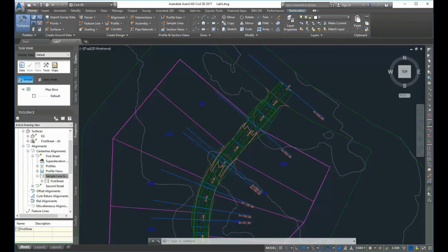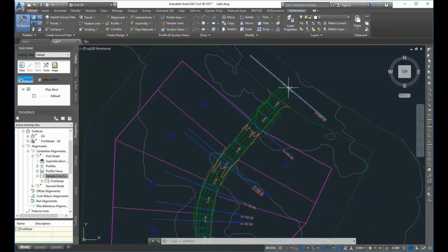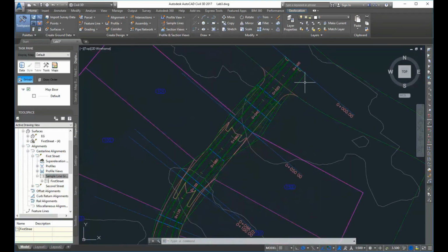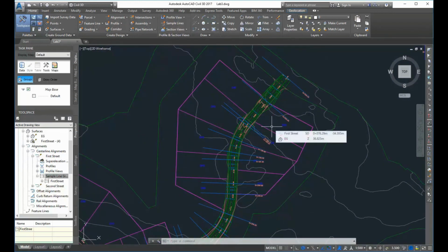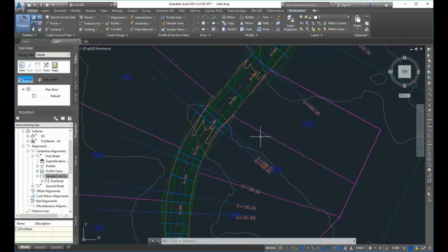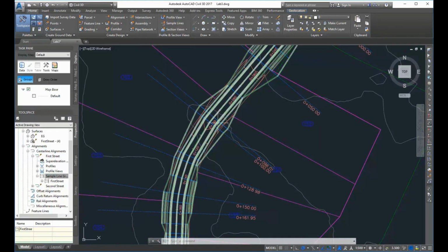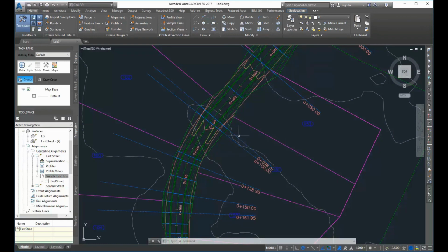Now when I talked about the swath width, I said that we saw it was 50 meters to the left and 50 meters to the right, and so that's pretty large, and so we get the full 100 meters. What we're looking for here is we need to make sure that these sample lines are longer than our daylight lines. So on your project it defaults to 50 feet left and right, and you can get into situations where it's not quite long enough. So I would suggest that you probably want to change those maybe to 75 feet on your project.